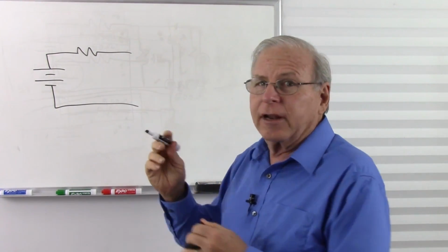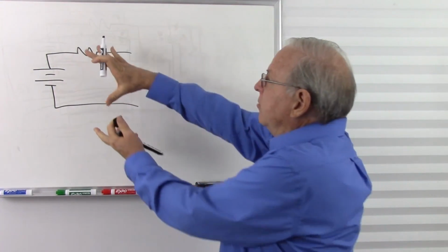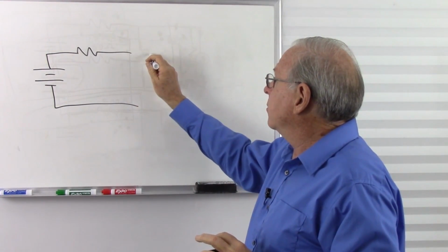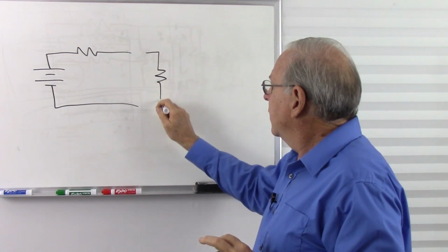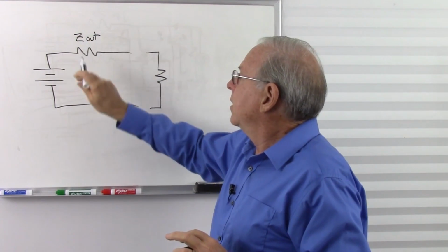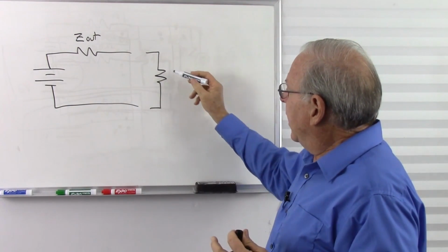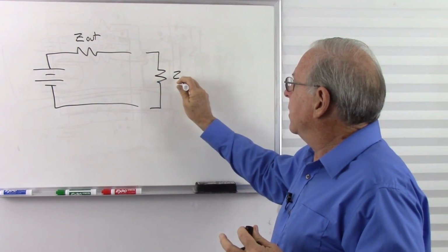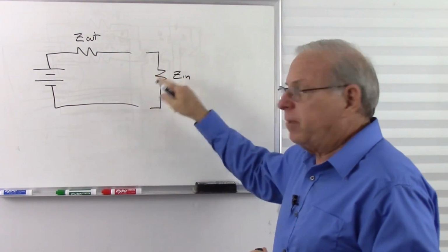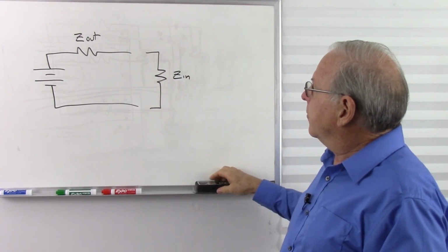And so that other circuit does not produce an output, it's an input, so it's passive and it takes the energy from the previous circuit. And when we do that, we have that represented by a single resistor. So here's our output impedance, just a resistor here, not the complex impedance we have in AC circuits. And over here we have the input impedance. So every circuit will act like that. So we have a circuit, and then the input impedance, of course, is the load that we put across there.